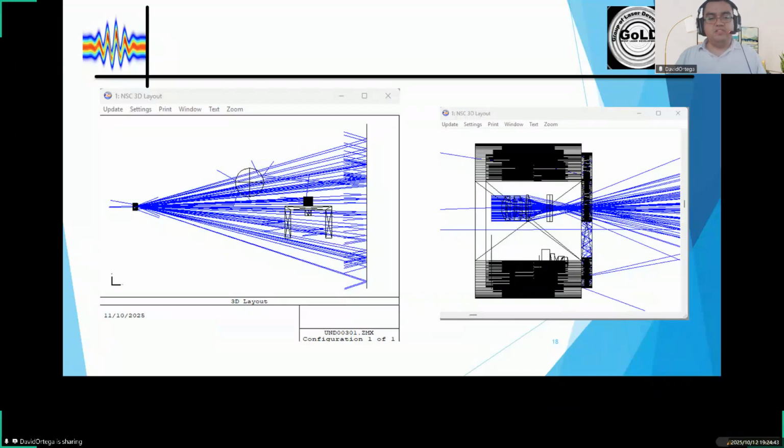Basically, when we simulate some system, in this case a real system, we need to specify every material. For example, these lenses are going to be like a diffraction grating. In real life, the PMMA material, which is plastic, has a cover like a layer, and this layer has optical properties that make a dispersive layer like a diffraction grating. But in the ZEMAX software, you cannot apply a diffraction layer to a component, so you need to add a diffraction grating in place of the component. When you put a diffraction grating, it is allowed to put it even in the material. If you put two lenses, it is going to give you some errors because there are some pieces that are crashing together, but the diffraction grating can be put exactly in the material, and this is going to be like the coating material.